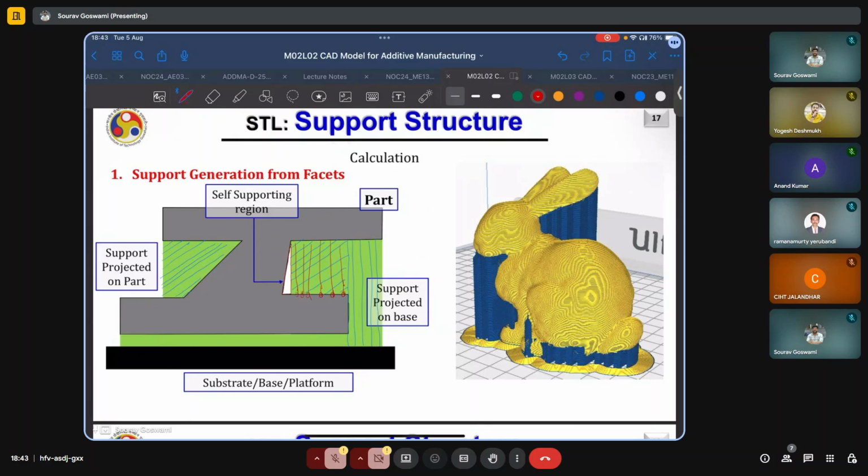In this case also, and also with the top surface by the way. Here it is coming in contact with at least three surfaces. And so, if these support structures are not removed properly, they will leave some artifacts or remnants on the finished part surface, and that will affect the final part finish or the part quality.